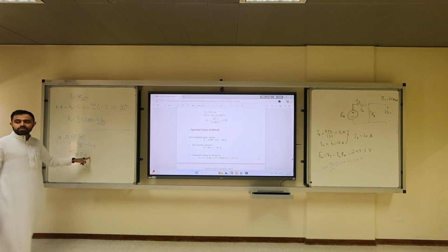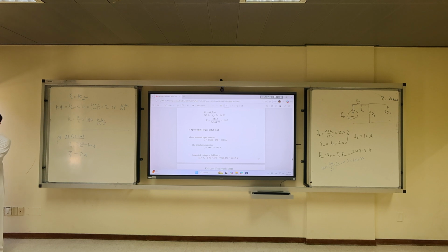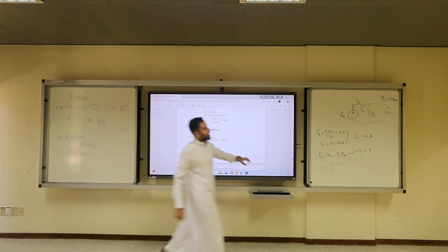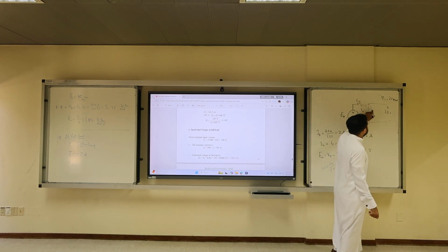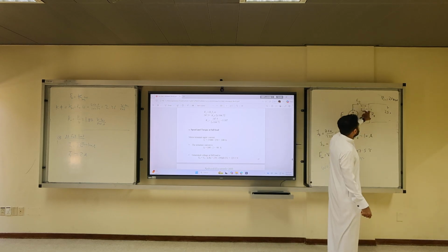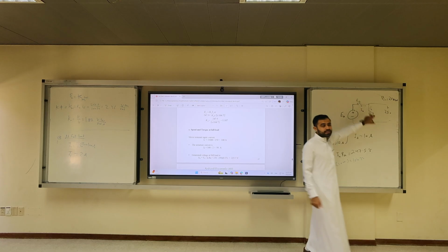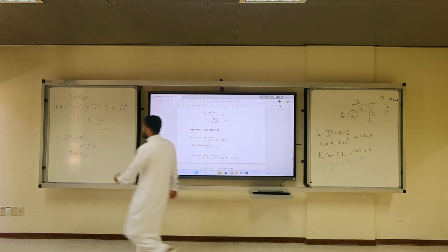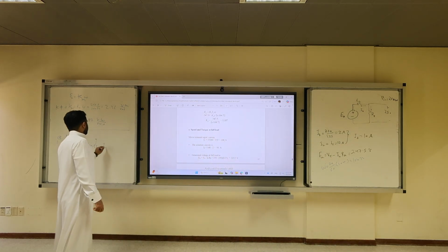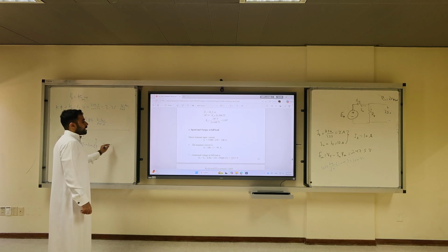The field will not change, because the same 250 is applied on the RF. Even if you connect the load, the only one that will increase is IA, it will be 98. So the full load armature current IA is 98 amp.